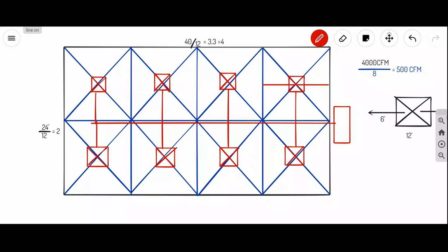After converting all these drawings into 3D layouts, whenever there is a clash between two drawings, suppose I am running a duct and there is a clash with the sewer pipes, he will suggest a change: change the sewer pipe here. When he suggests a change, we will change it, but we see whether it is affecting our calculations or not. Like that we make clash-free drawings and check them using Navisworks.